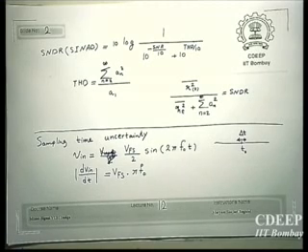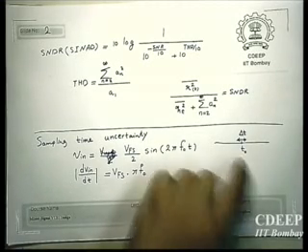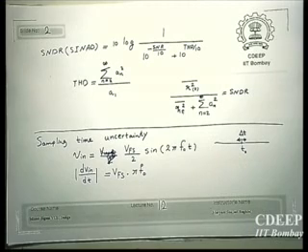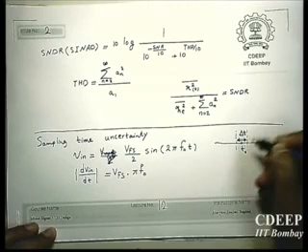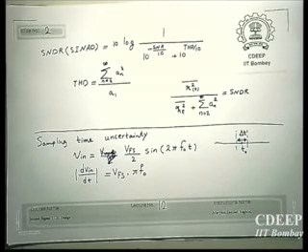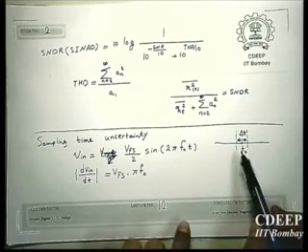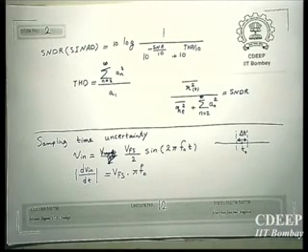Nobody can claim the system samples at exactly this time. We call that uncertainty delta t. Therefore, we would like to reduce it as much as possible, right? So there is an ambiguity window around t0 and your real sampling point can be any point in this interval. How small can this delta t be?